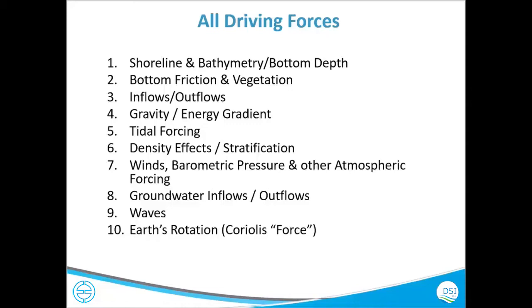They might not be accurate, so you might have to look at your slice and longitudinal profile and see how it looks. If you think it should be a slope, but you see there is a bump somewhere in the bathymetry, then your water is not flowing in the right direction, then your model is screwed.